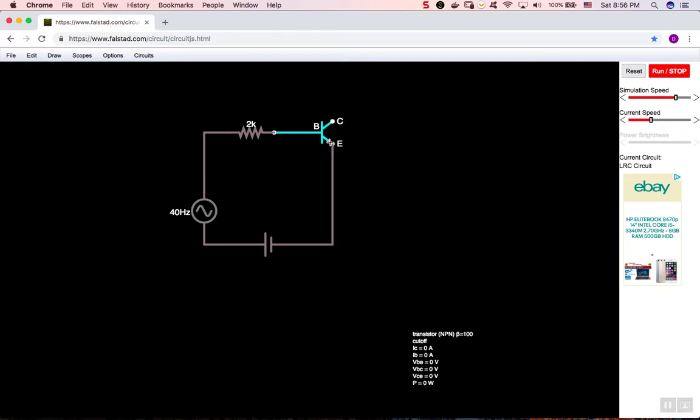On the other hand, the current in this branch, the branch that I'm highlighting right now, this branch that's below the emitter, it's going to be the current IB and IC together. And IB plus IC is the current IE. So it's going to be the sum of the current IB and IC, but the current IB specifically is going to flow here and then turn to the left. Then here it's IB only, here it's IB only, here it's IB only, and here it's IB only. Okay.